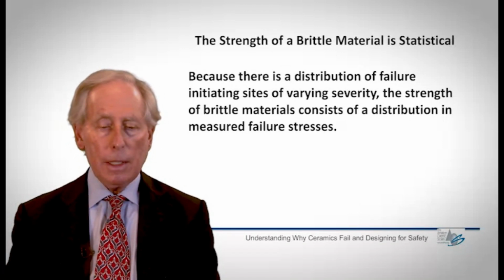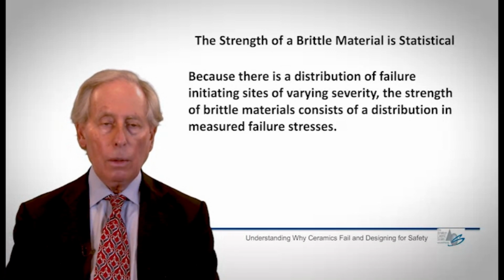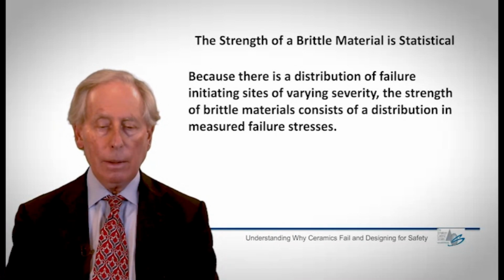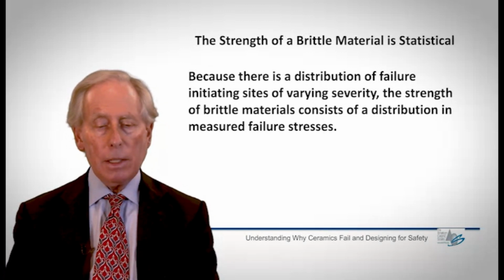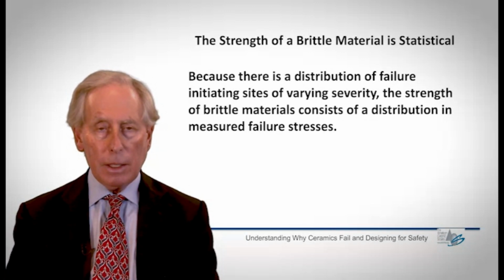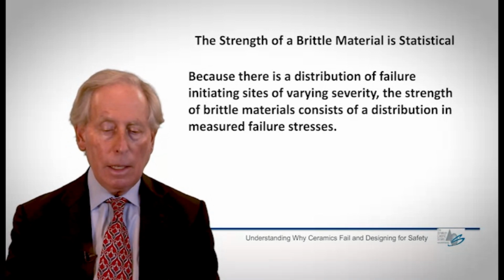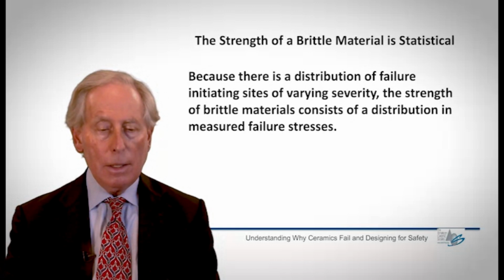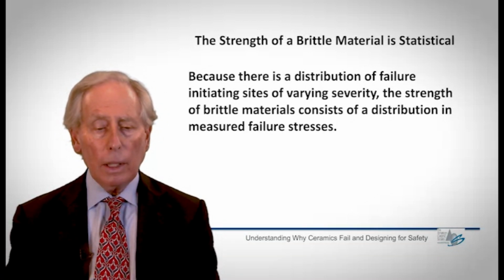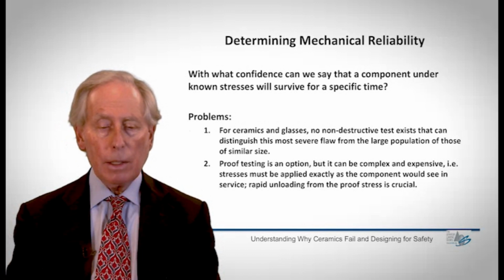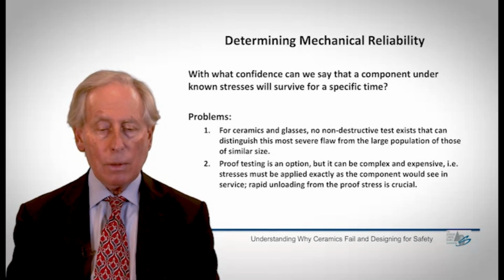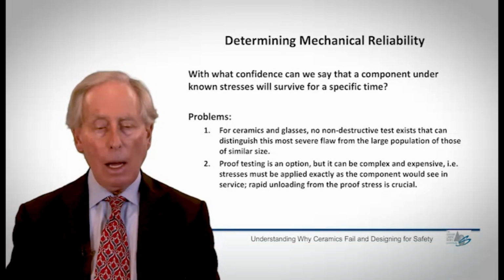So this idea runs completely through the whole section and is important for every aspect of analyzing the fracture behavior of ceramic materials. And because there's a distribution of these fracture initiating sites, quote unquote flaws, which have varying severity, the strength of brittle materials consists of a distribution in measured fracture failure strengths. That is an extremely important concept. And our goal is to determine the confidence that we can say that a particular component under a known stress will survive for a particular time. How can we do that?